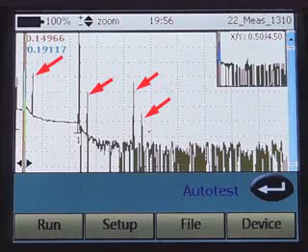You can see a second version of that ghost, and then a ghost of the 1 kilometer cable, and yet another ghost of the 150 meter cable right in the center of the trace. This is a common occurrence when you use too high-powered a test pulse.